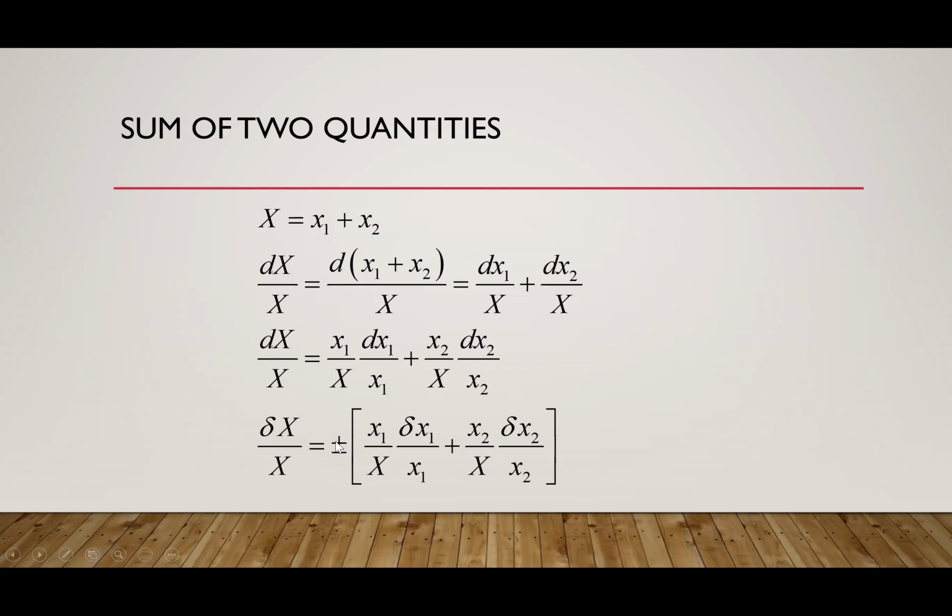And plus minus, always we are going to substitute in this calculation, because your error could be either in the plus direction or it could be in the minus direction. Deviation can be either on the positive side or on the negative side. That is why in the final quantity, the error could be either plus or minus. So similarly, if I know the relative limiting errors of these individual quantities, I can always calculate the relative limiting error of the final quantity.